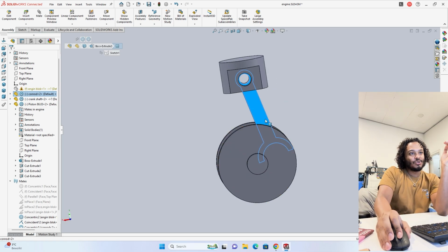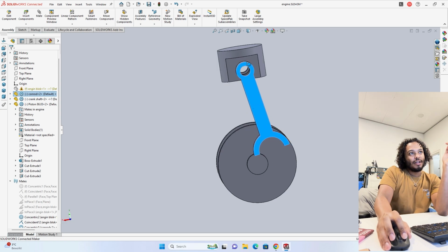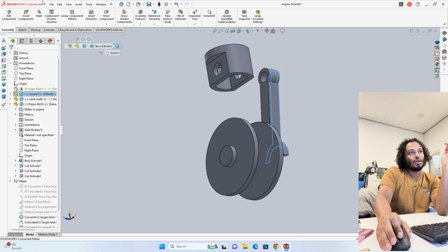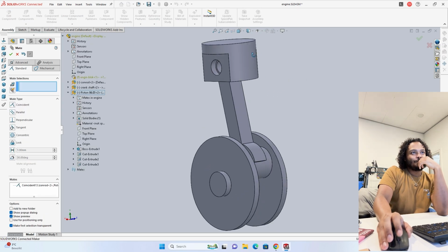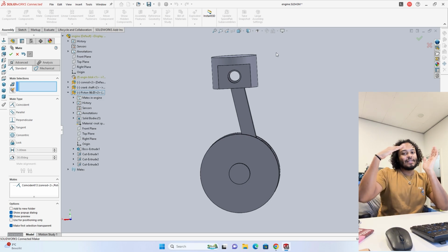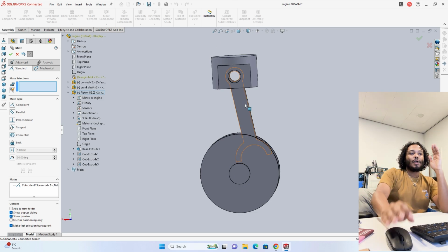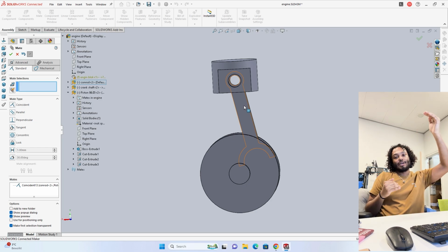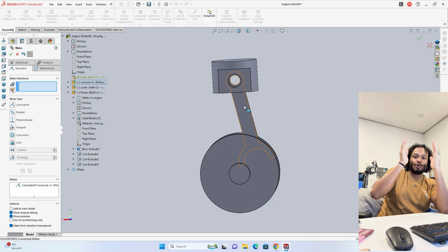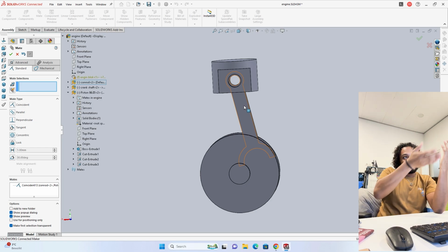You can see here, as soon as this would move upward, it is pushing the piston against the side of the cylinder wall at an angle, and that angle gets less steep the longer the connecting rod is, because it will sit more parallel to the cylinder wall in a way.